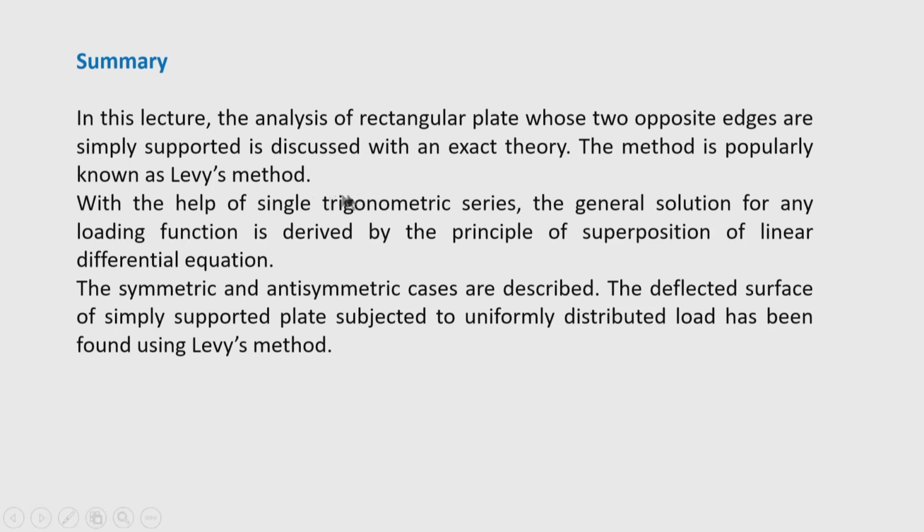With the help of the single trigonometric series, the general solution for any loading function is derived. We have derived this general solution for the function y, for any loading condition. The particular integral of course has to be found out depending on the nature of the load.